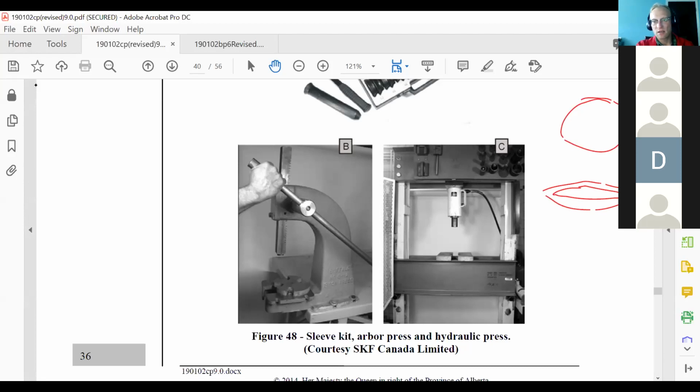If you take your old bearing race and a nice, decently thick grinder cutting disc, you cut into the bearing. As soon as you take that grinder disc out, the bearing will shrink in just a little bit. And it'll be just enough so that it'll still sit very nicely on the race of the same size, but it won't get stuck in the bore. It's just small enough.